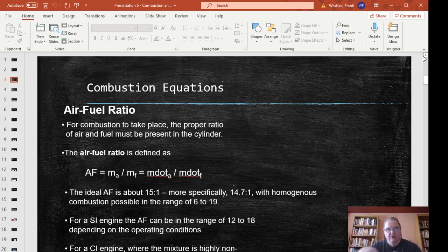We are using closed loop control based on the oxygen sensor in the exhaust to control the fuel pulse width, or how long the fuel injector is open, so that if you take the mass of air that comes in, you're putting in, hopefully homogeneously mixed in there, 1 part of fuel to 14.7 parts of air. And that was the goal of the control system.